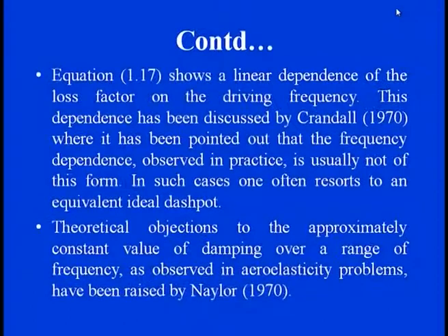So when we are trying to formalize the loss factor, we know that the system parameters and the operating conditions are both responsible for it. But there are some theoretical objections to approximating a constant value of C, that is the damping, over the range of frequency.